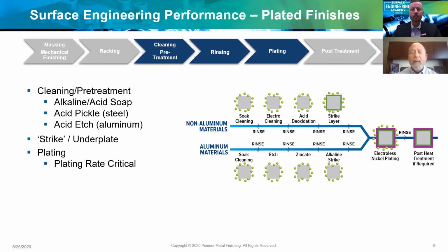One of the most important things, though, in this process that can't be overlooked is the purity of the rinses and the proper dwell times in these rinses to make sure we're not contaminating the different solutions or trapping chemical residue in blind areas, recesses. So it's not only controlling the chemistry, but it's also understanding which chemicals need to be used and then following through with a proper process.